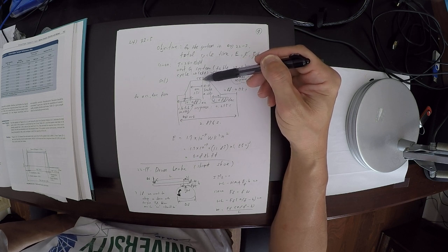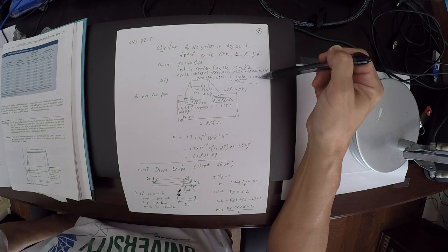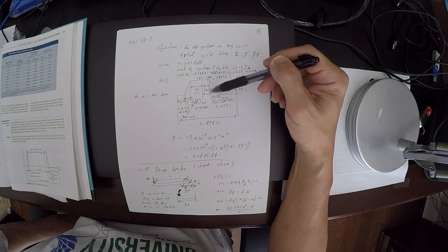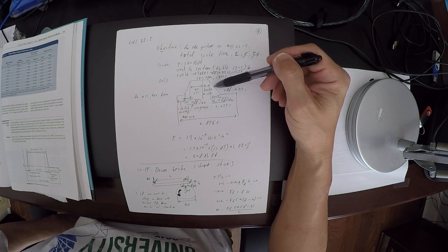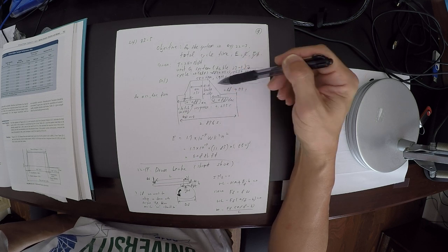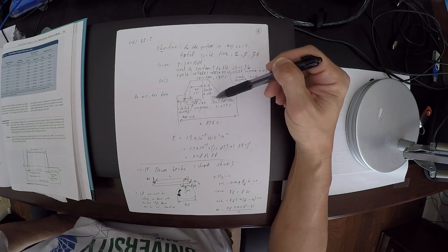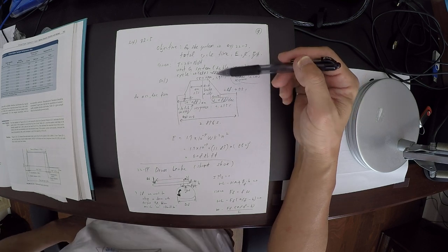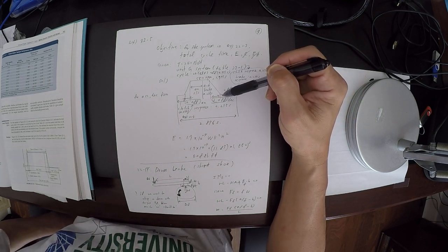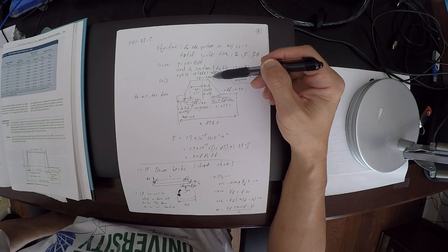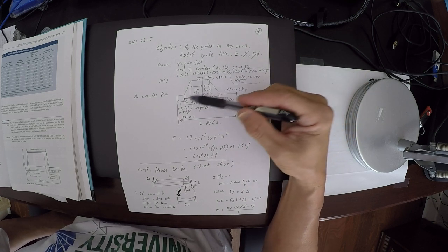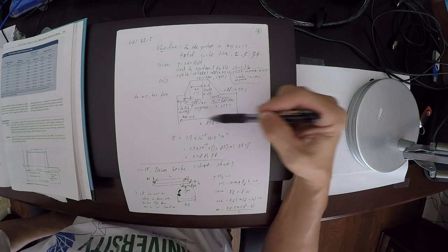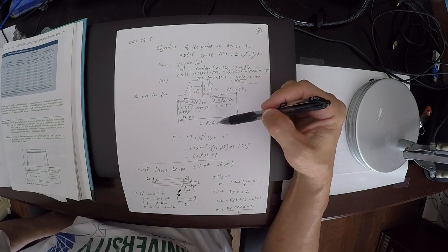You apply the brake right here, and then the brake response time is again the same as the clutch response time, which is 0.235. And then because you decelerate, it's going to be decelerating at the same rate as the acceleration. So we have to apply the same time of 0.088, and then after this, the whole system will be off for 0.75 second. So if you add all this up, the total cycle time of this system is 2.896.